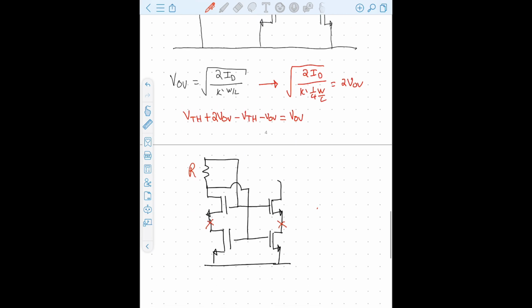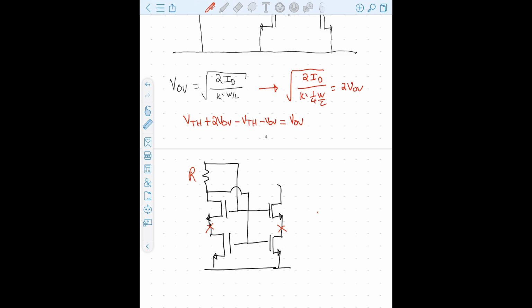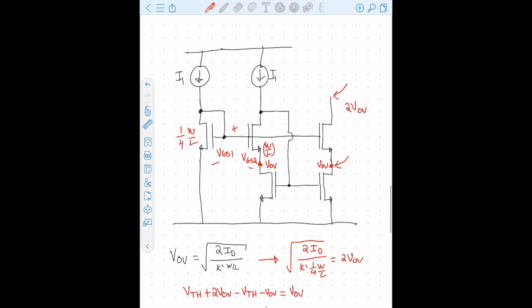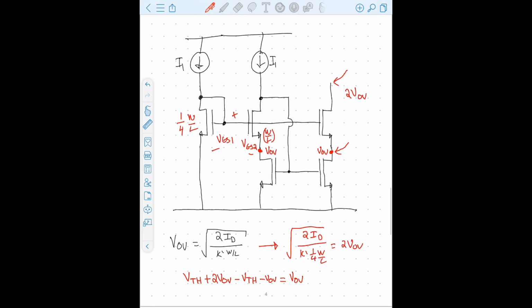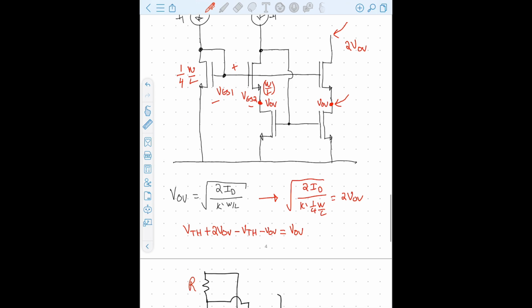Additionally, having that resistor there is going to consume likely a lot more silicon area, and that's expensive. Oftentimes we don't have much of that available. So wherever possible, you don't want to use these resistor components. It's better to bias with the FET, and there's more than one benefit in doing it in that manner.